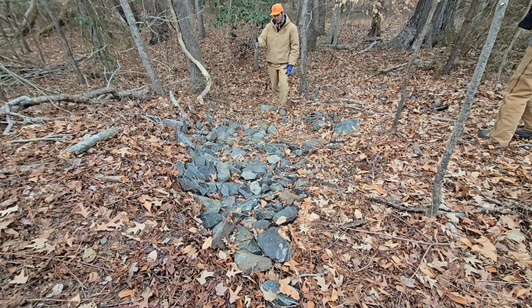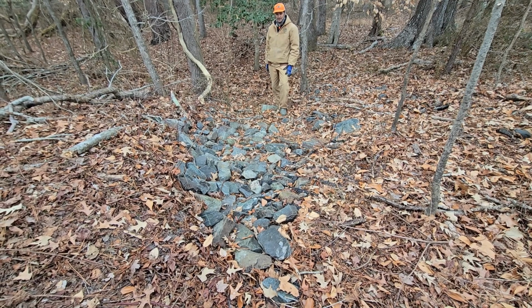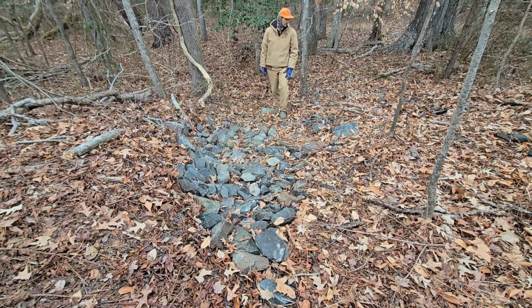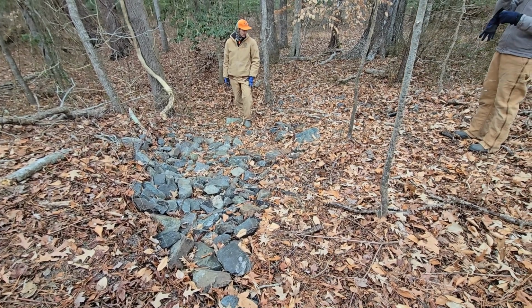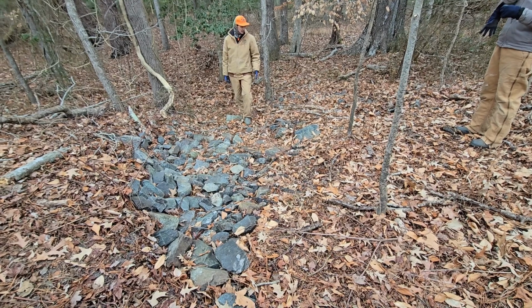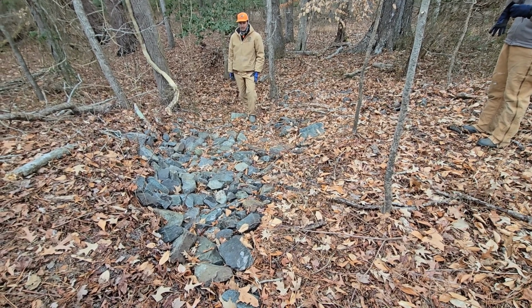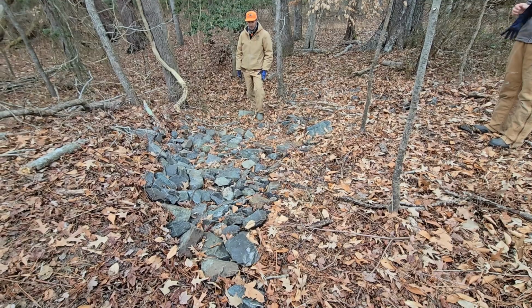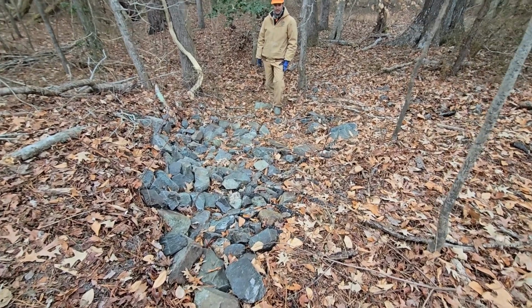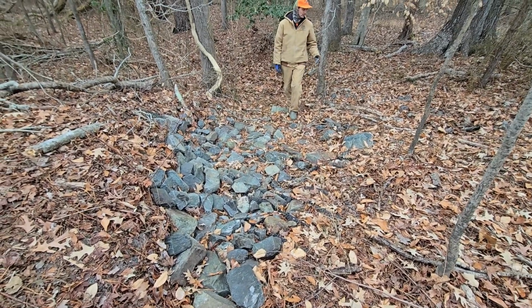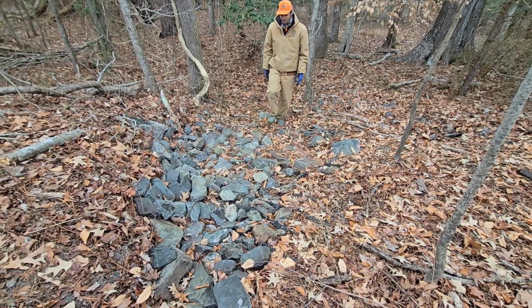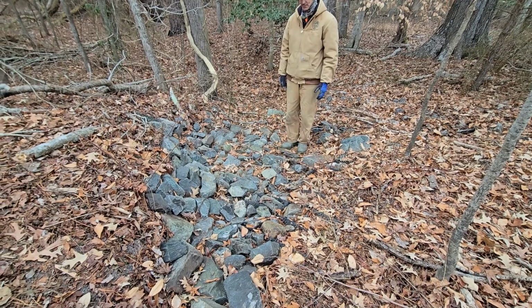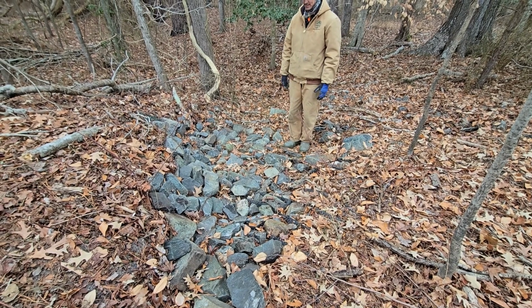So we were noticing spots of erosion and some exposed soil, and we noticed there's a pile of rock over here that wasn't really receiving any water and wasn't really doing anything, wasn't moving much. So in order to armor the part of the spillway that's receiving most of the flow, we decided to shift some of the rocks over to this main part of the spillway, so that way we could get some nice even sheet flow.